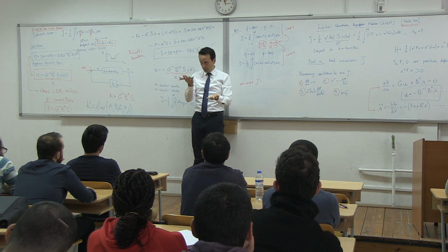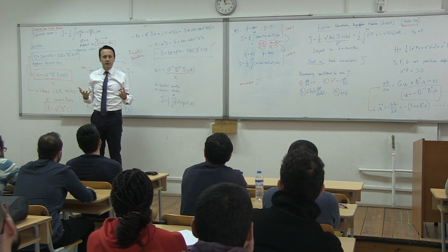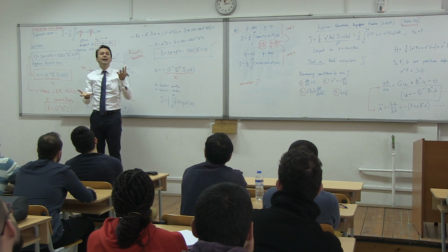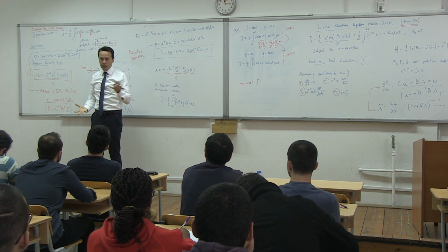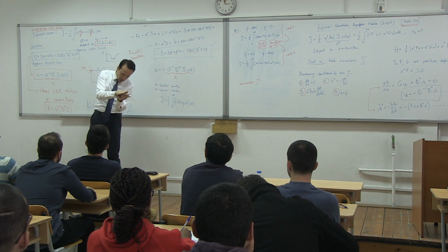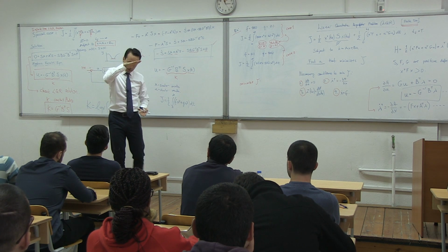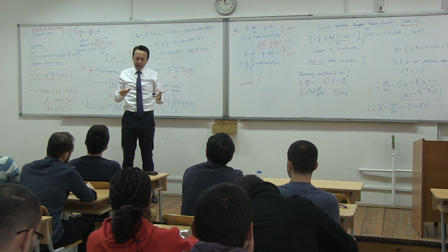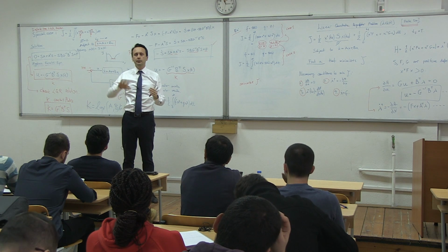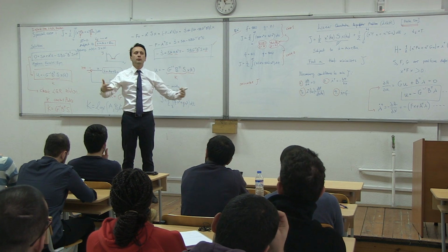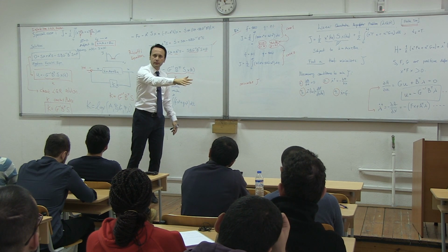So you are going to make that choice. Okay? We call this f and g weight matrices. You are giving weight to one or the other. Either you want the controls to move a lot and x's will be constrained, or you can say the x's are free and I want the controls not to move too much. If you think about it from a controls point of view, from a controller point of view, if the control system doesn't give too much input to the ailerons and elevators, then the aircraft is free to move. Okay?